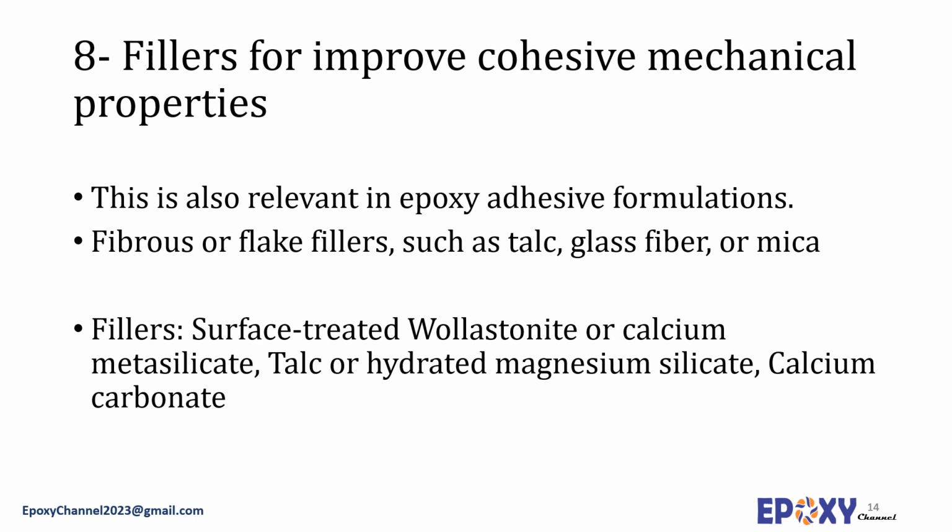Surface-treated wollastonite, or calcium metasilicate, which is a fibrous mineral filler, is also employed to improve adhesion to the epoxy matrix. It can be applied at relatively high loading levels, which yields high strength and improvement in moisture resistance. Talc, or hydrated magnesium silicate, is another mineral that is used to reinforce epoxy adhesives. It has a plate-like structure that provides good stiffness and creep resistance at elevated temperatures.